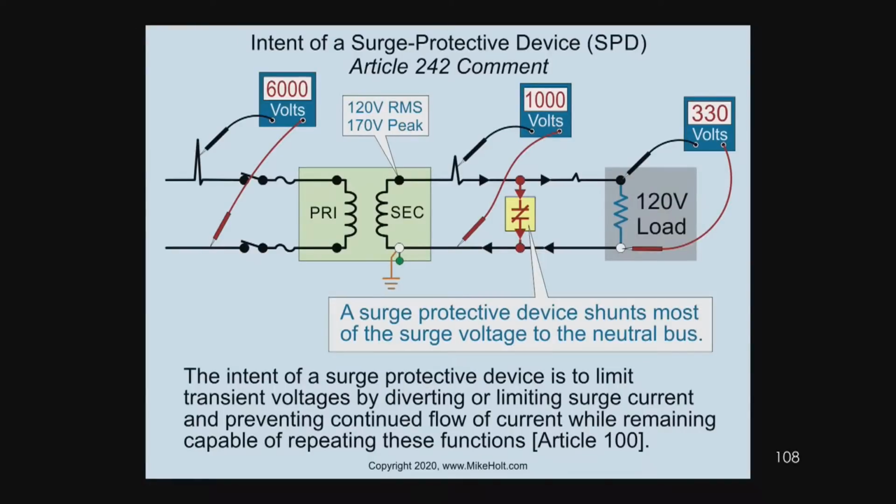So John, talk to us about that. Yeah, so it's like any product, there's good and bad. Most of them are good, but there are some that have design issues and manufacturing issues. One of the problems that we see with surge protection devices is due to a device called an MOV, and that's a solid state component that's actually doing the conducting when the voltage exceeds a certain value. So in the case we have on the graphic, if the voltage gets above 330 volts or so, it starts conducting. And like I said earlier, it's a discrete device. It can only handle a certain amount of current.